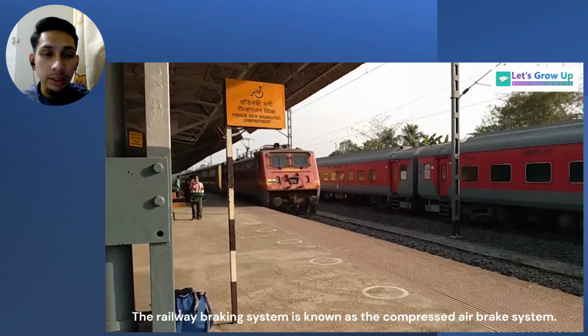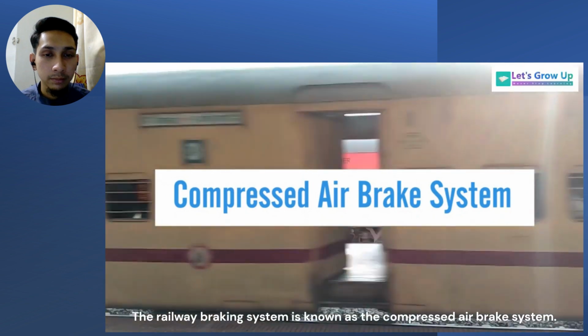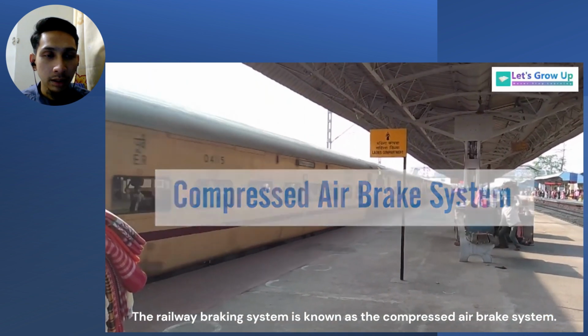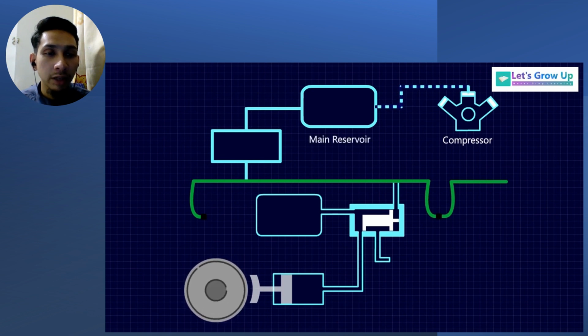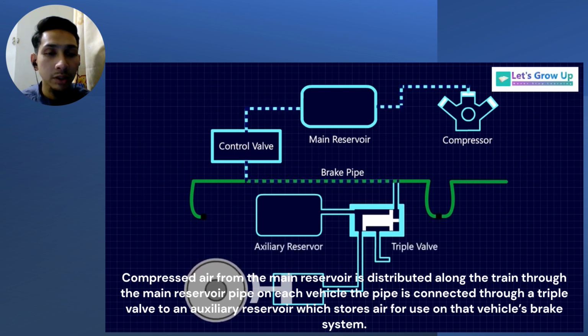The railway braking system is known as the compressed air brake system. It is a system where air is drawn into a compressor and stored in the main reservoir. Compressed air from the main reservoir is distributed along the train through the main reservoir pipe. On each vehicle, the pipe is connected through a triple valve to an auxiliary reservoir, which stores air for use on that vehicle's brake system.